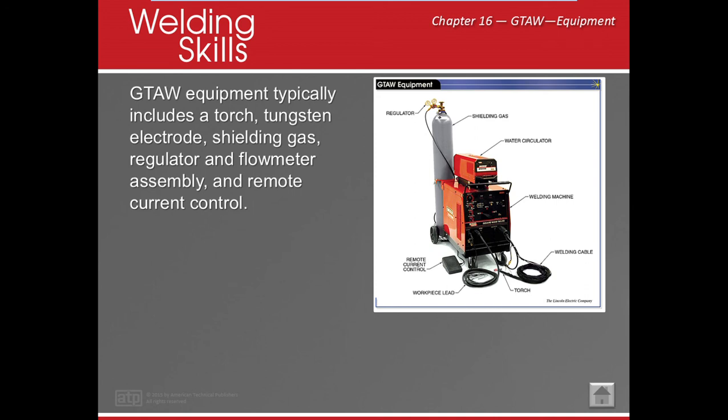Okay. Of course, we always need gas. All right, so generally, 95% of the time, don't quote me here, we're going to use 100% argon for TIG. Okay, there's other things that we can use, but let's just keep it there.